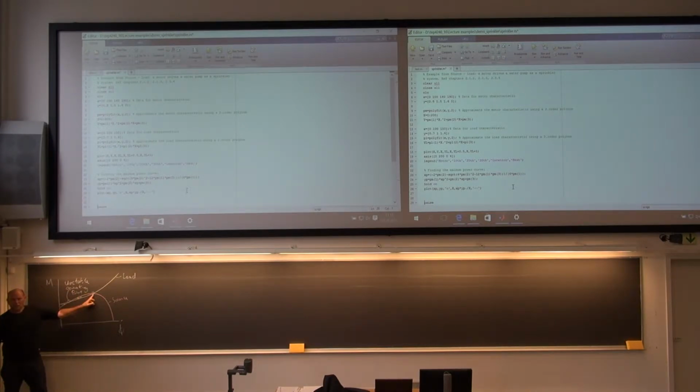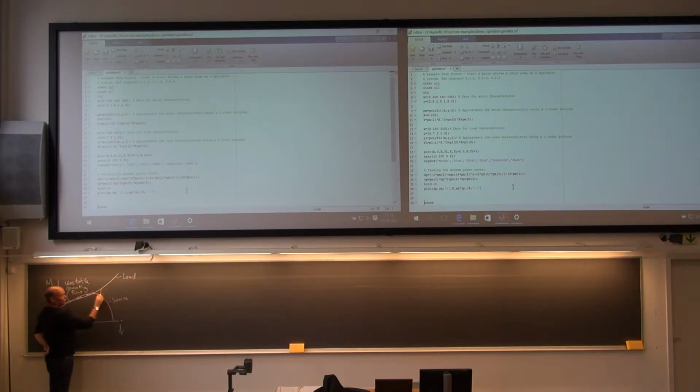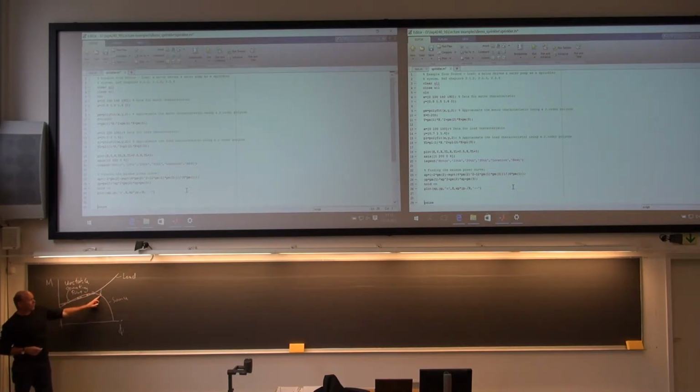What about this one? Well, here you will now get the opposite effect. You go a little bit to the left. Then your source is stronger than the load. It will accelerate up again, and move the rotational speed back to where you started. Or if you go a little bit above this point, to the right, a little bit too much, then the load is stronger than your source. You are lacking energy here to keep this speed. Things are going to slow down, so it will push you back again. This is a stable operating point.